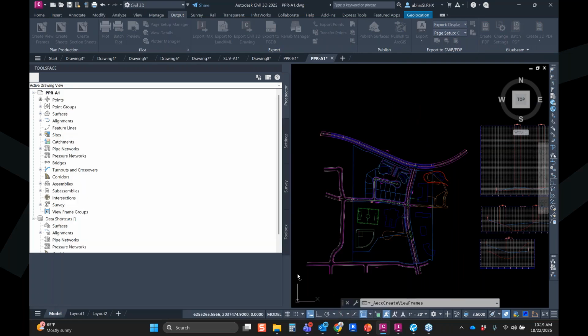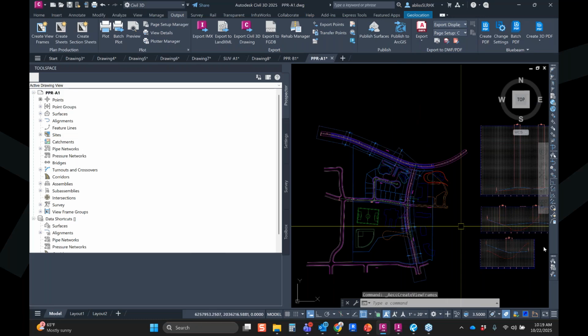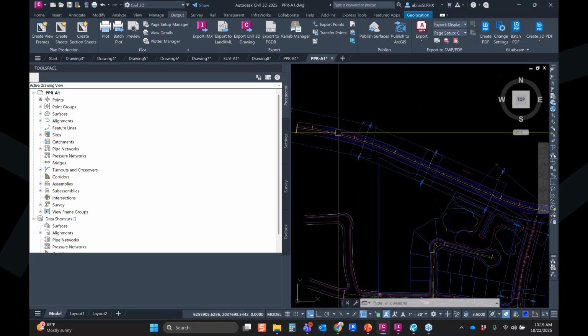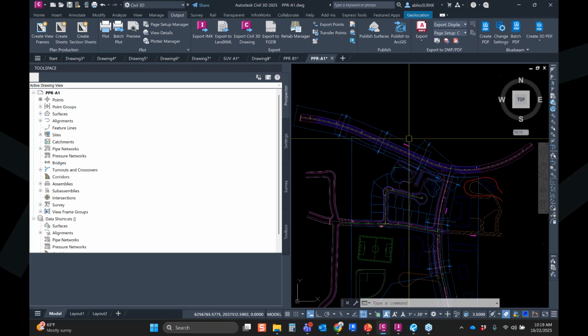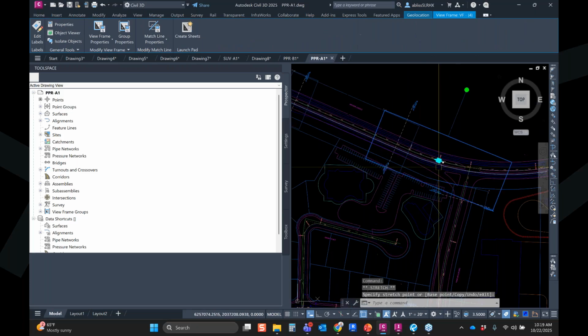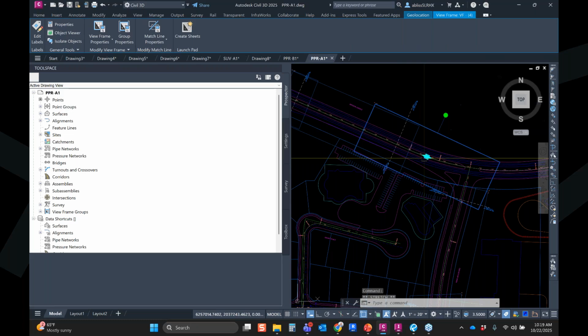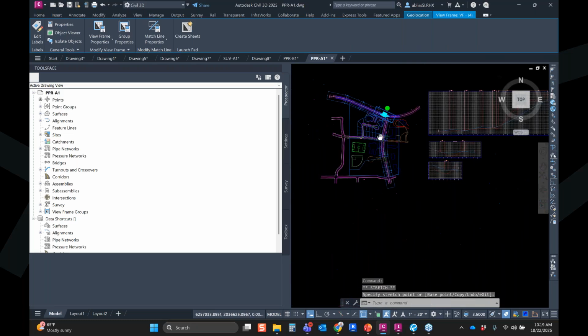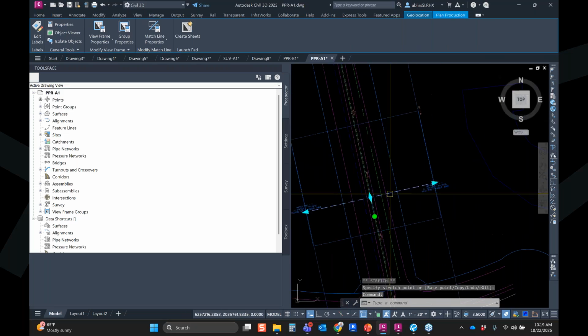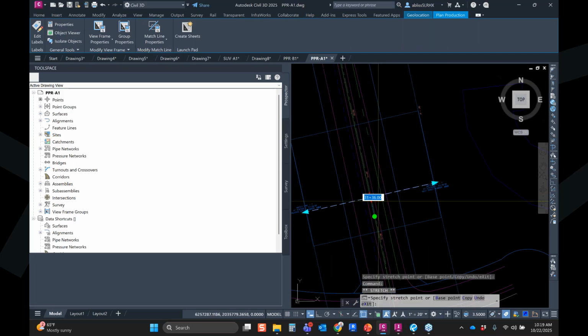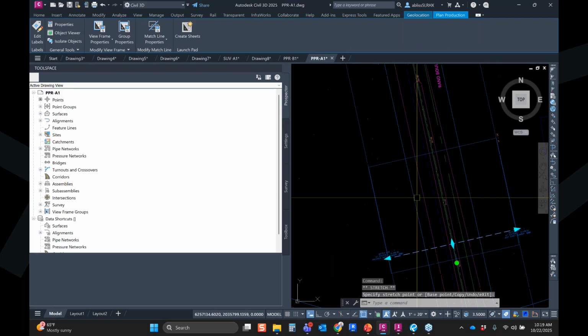And let's take a look. And here we go. We got all of our view frames, all of those viewports preset with the match lines all done, fully automated. So that's about half the work that you would go through. And it's all done. You can make any kind of modifications you want, rotating them, sliding them up and down. If they didn't fit quite how you anticipated, you can do all of that kind of work. And you got those match lines there as well. If you need to move them, those fully move and will go wherever you need them. So really cool automated process here.